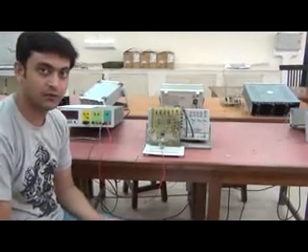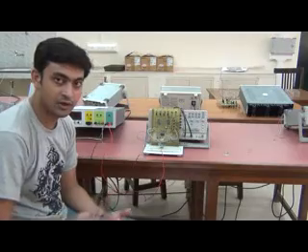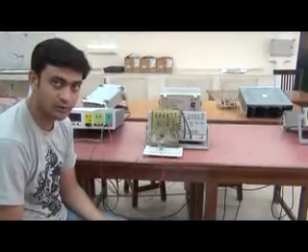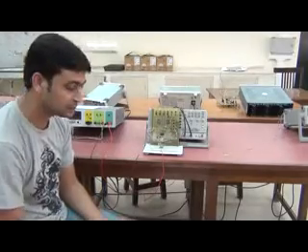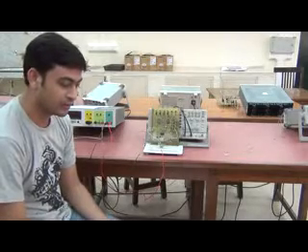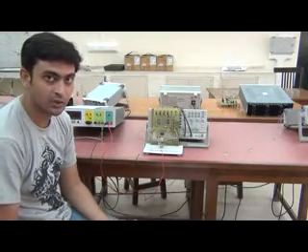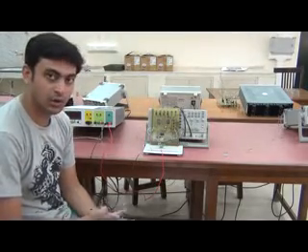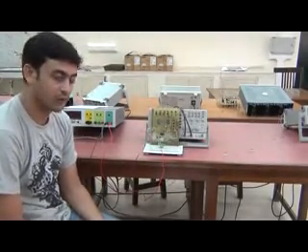In this divide by 4 counter, we will have the sequence going from a higher value to a lower value. So we'll have the sequence 1 1, 1 0, 0 1, 0 0, and again back to 1 1. This pattern will keep on repeating, and that is why this is called a divide by 4 counter, since we have 4 different states, that is 3, 2, 1, 0. We have 4 sequence numbers, and this pattern will keep on repeating itself, and the clock is the same for all the flip-flops, hence it is called a divide by 4 synchronous counter.